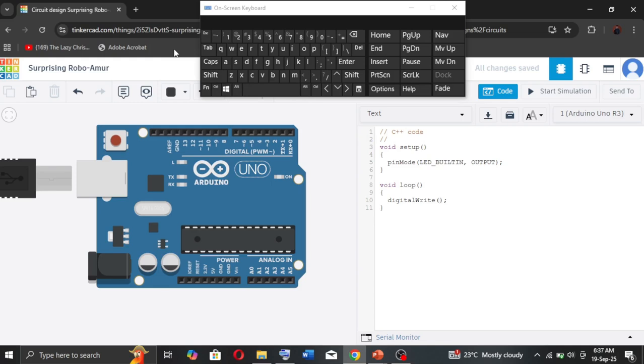The device we want to turn on and off depending on the case is our LED_BUILTIN. So we repeat exactly the same thing. That is why I copied from there. Then we put a comma. Now, for it to blink, we have to first turn it on, right? So put a special keyword called HIGH.